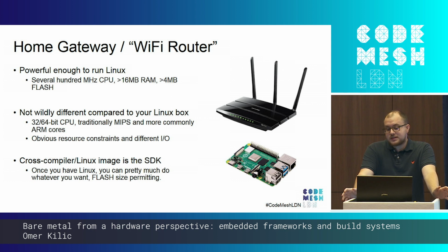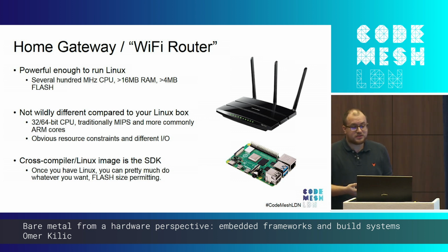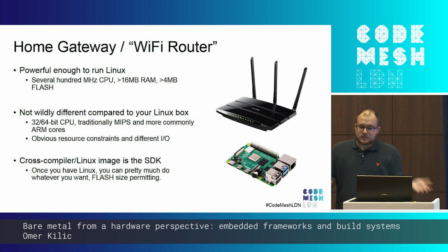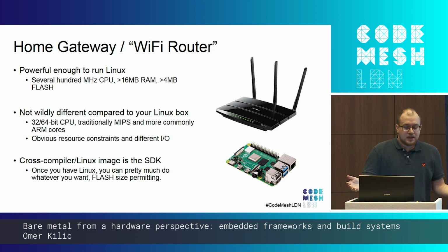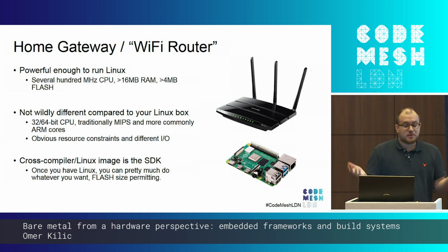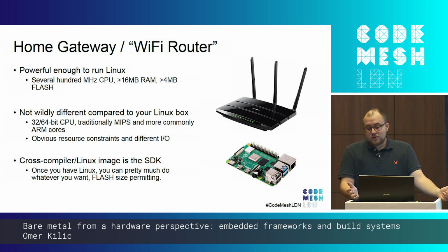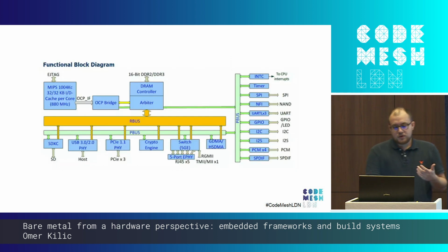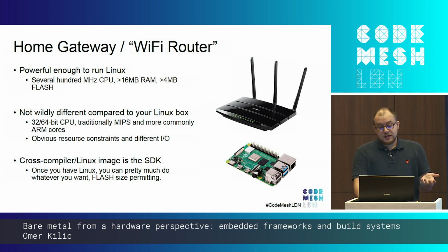So development on these is done not too dissimilarly from how you would just generally develop stuff on Linux, except you probably will have to take into account that you might only have a few megabytes of flash to fit your stuff in. And also, you probably are not going to install Ubuntu on this tiny device, except if you have like a micro SD card or something. Actually, sorry, I skipped a slide.